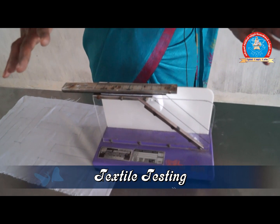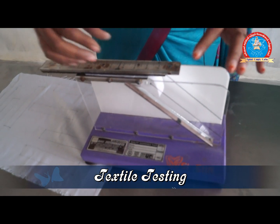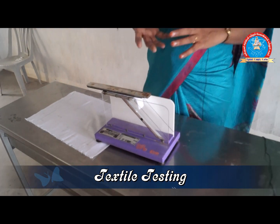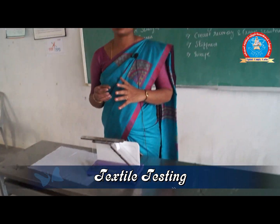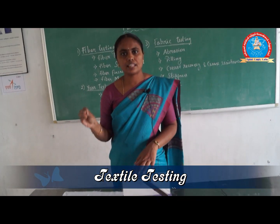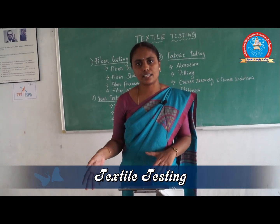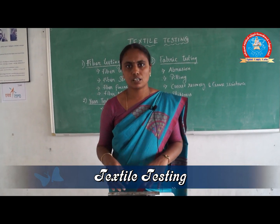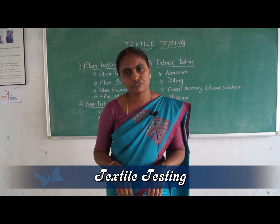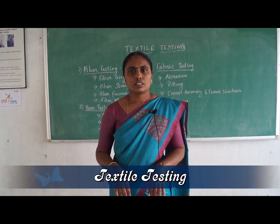After we collect all the measurements, we calculate the mean value, that is, the average value. So the warp-way bending length average value is 42.7, and like that we note the measurements. So this is the procedure for the Shirley stiffness tester and also its working principle. Thank you.